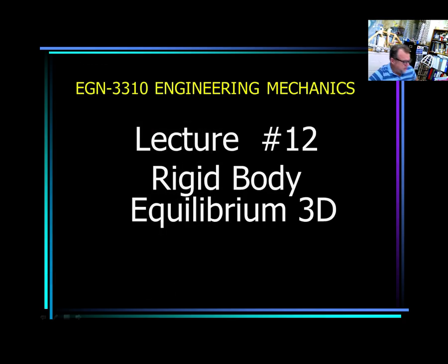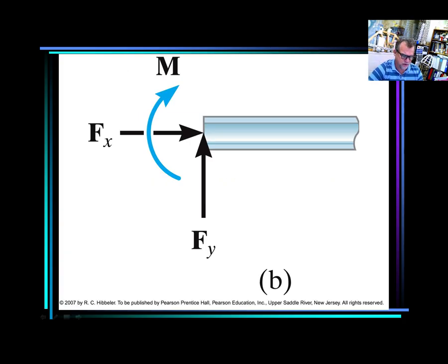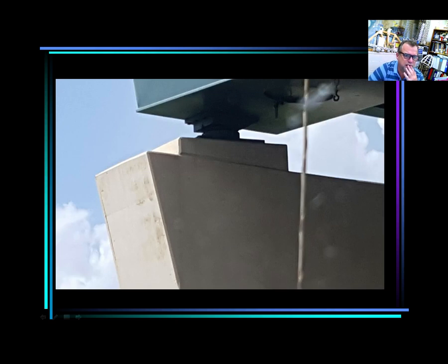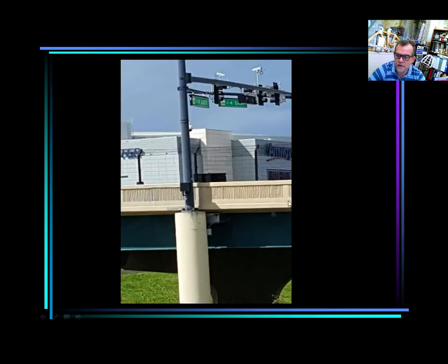So today we're going to do the same thing, but now we're going to be working in 3D, in space. Okay, but some examples. Look, this is 3D actually, but you see this is a real support in a bridge, and basically depending on how this connection is here, it could be a roller or it could be a pin, but I think it's a roller that is acting here. This is a pin, obviously, and you don't need imagination because you can basically see here that it is a pin completely. What about here? Well, here is a fixed support, obviously, in 3D.